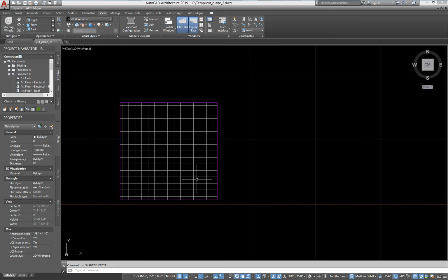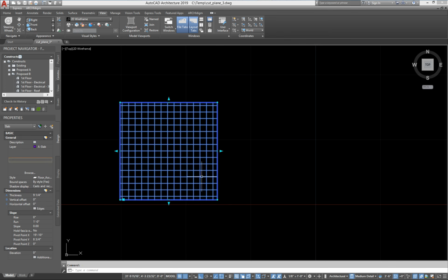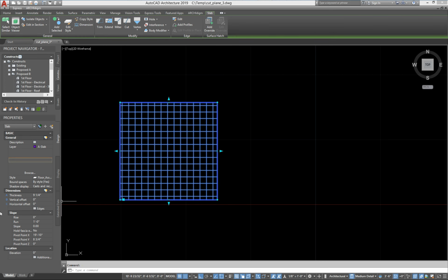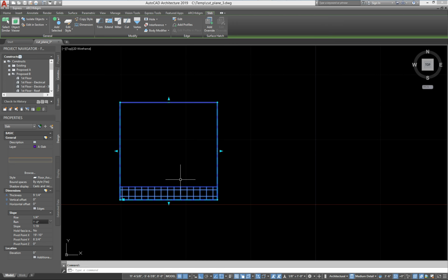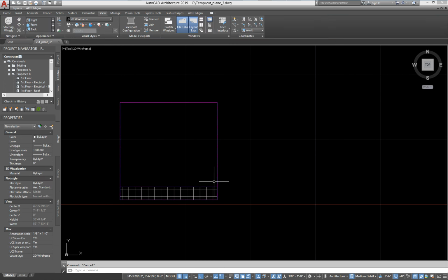Now here comes an interesting problem, which will kind of walk me towards the next subject, which is the roofs. But if you take a floor slab and you decide, I'm doing a ramp, and I'm doing a ramp at about 1/4 per foot, it's like some kind of accessible ramp, weird stuff starts to happen, right? Like this. This is probably not what you were expecting to see.